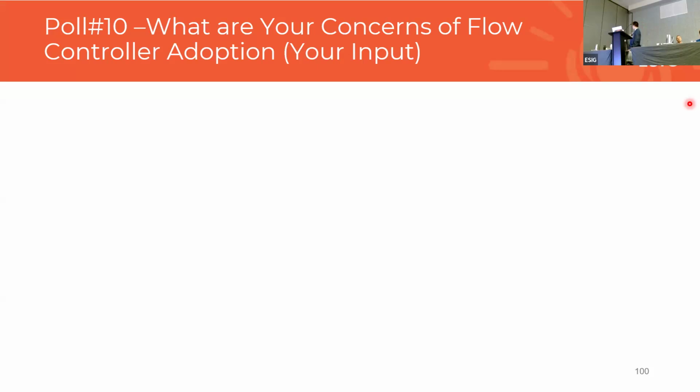But there was a second part of your question too, I think. Oh, for reclosing shots. When it loses power, it is going to wait for an adjustable amount of time, similar to a DER device. If a utility wants it to come back on very quickly after an event and get back to work, it'll do that. But by default, it's programmed to wait for about 5 minutes of stable voltage, similar to what a PV might do, before it re-engages and starts balancing the circuit again.